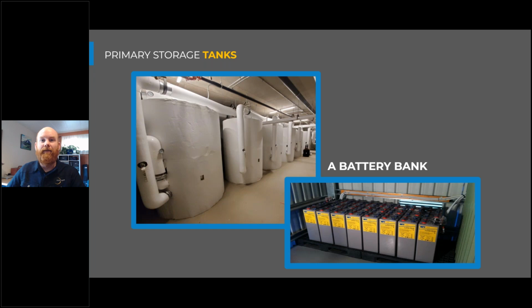And typically it makes sense to connect them in series when we're working with single pass primary heat pump water heaters. And it might make sense to connect them in parallel when we're working with our multi-pass heat pump water heaters. And that really ties back to the discharge water temperature out of those heat pump water heaters. And in a single pass cycle, we can always guarantee that water to be above 120 or that usable delivery temperature.